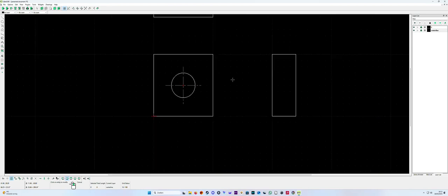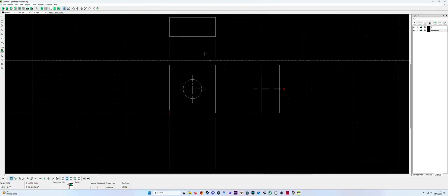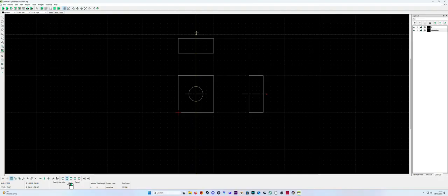Okay, then you want to place the hole in the side. But if it's later on, we are going to explain it. If you want to draw the hole here in the side also, the first thing you can do is put a straight line, put the center line through it like that. Also on top, of course, the same thing. But now you cannot draw a line like that, because then it looks like there is something on the outside. So we must